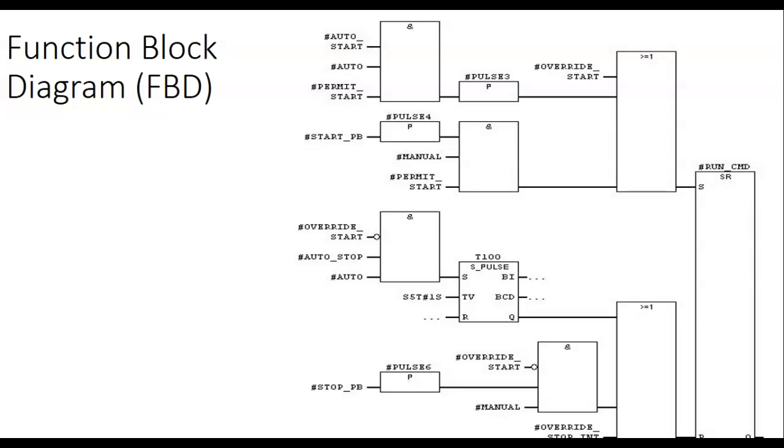This is electronics, guys. If you've had digital, then this is digital, except they use the ISO symbols instead of the symbols that we use over here. So this is an AND operation. If I wanted this and this and this to go true to generate an output, then this would be perfect for me. So if I came up through digital or electronics and I didn't want to learn motor controls, then this would be the language that I would choose.